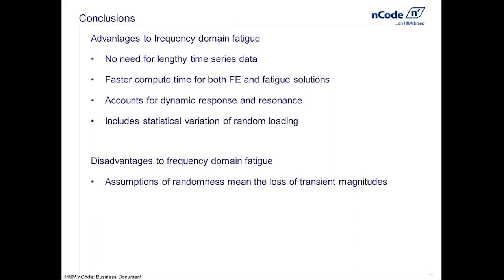So just keep in mind that if you have transient or impact loading in your actual loading data that you're trying to apply to this part, we're going to wash out transients in going into the frequency domain. So with transients, you'll want to stick with the time domain. And to be honest, one of the beauties of this approach is that we could actually analyze some loading scenarios in the time domain and some in the frequency domain.